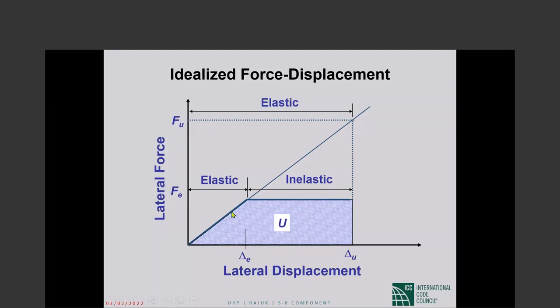Initially, we are showing elastic response of this particular structure to this particular earthquake. Elastic does not have to mean force proportional to displacement as shown in the picture. There is nonlinear elasticity, which is fine. Elastic really means no residual displacement. The earthquake passes, we get our structure back intact, no damage to be repaired.